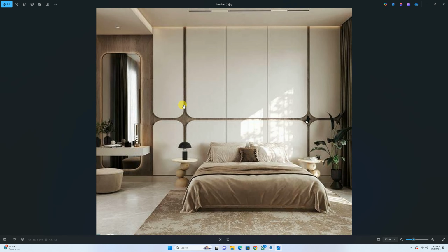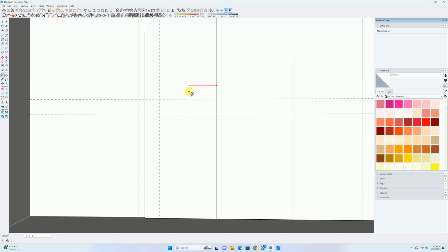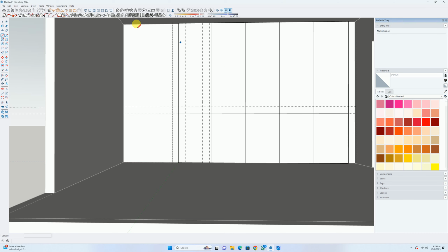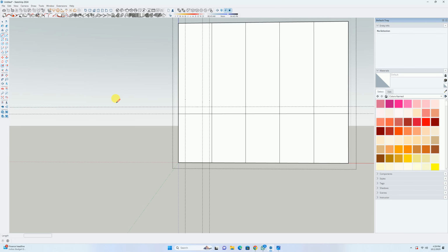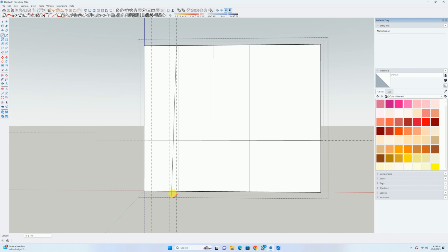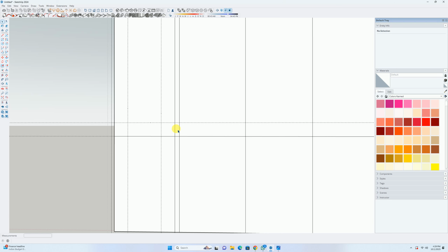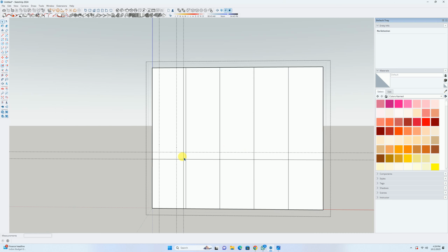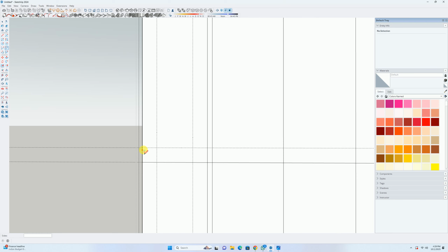As we are reducing the surface, right? So first of all, we'll create a gap of about 2 inches. Then again, we'll create a groove line for 6 inches. Then we'll go to the component edit and click on hide rest of the model so that the other elements may get hidden away. Now we'll create an edge over here and we'll use the R command.